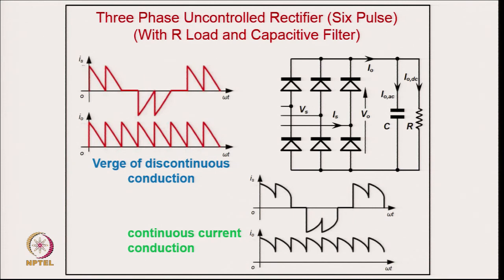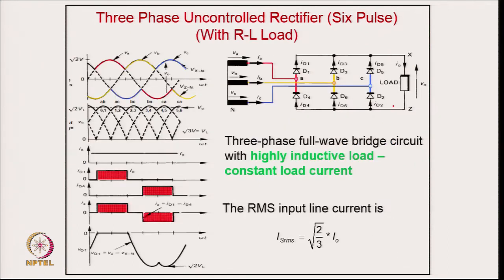And if it is a bridge and you are putting a capacitive filter, you will be drawing hardly two notches, and even a discontinuous notch may be there when a capacitive filter is used. We will discuss many problems of such nature. So it draws quite a large amount of harmonics, even the THD may be 60 to 65% or so, depending on the load nature also.